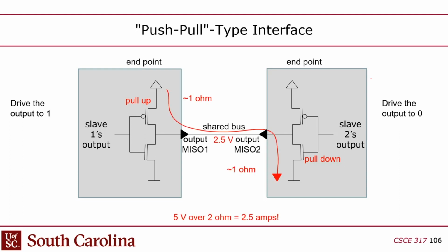So you'd end up with a lot of current. You'd also end up with, if it's a 5-volt system, the output in between. It'd be like 2.5 volts or so, because you create a voltage divider that is roughly like having a resistor going up to VDD and a resistor going down to ground that are roughly the same resistance. So the output there would be about halfway, and that would be an undetermined logic value, and you'd have a lot of current there.